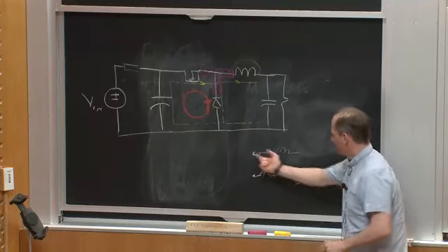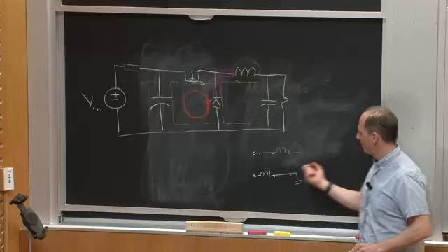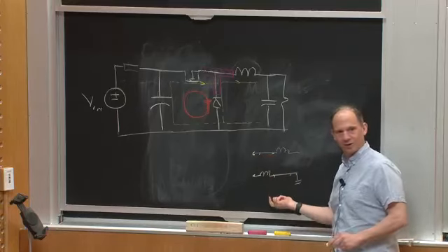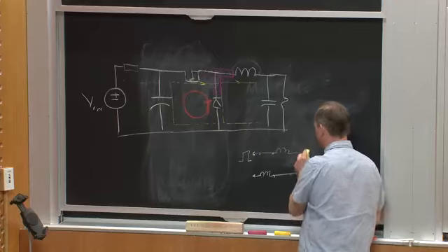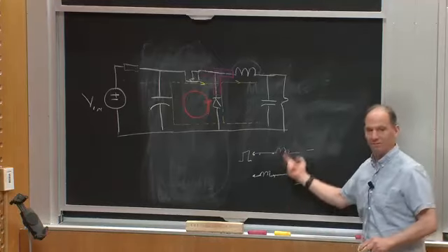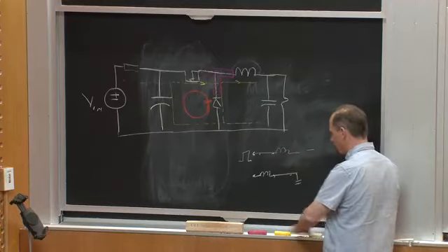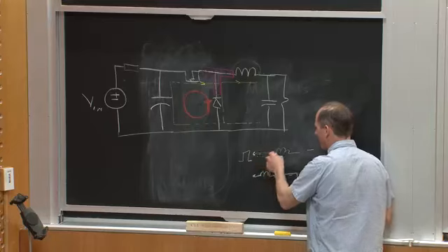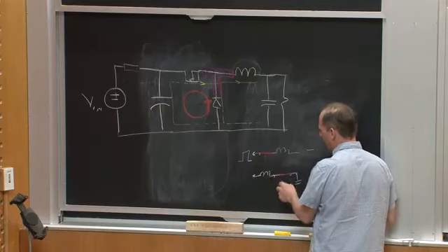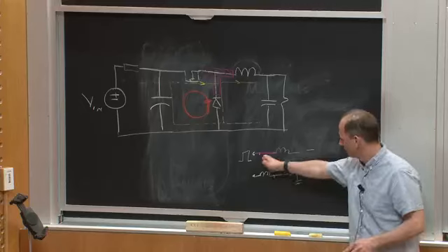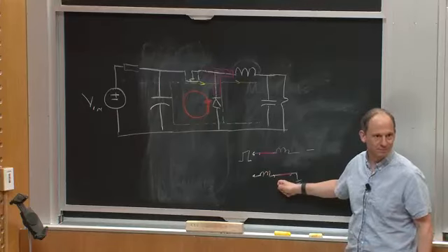These two things seem the same because the lead's either in series with the inductor on one side or the other, but this node is flying up and down, and this node is about fixed in voltage. So to the extent that this is forming a capacitor plate to other stuff, and this is forming a capacitor plate to other stuff, this is much worse than this one, right?